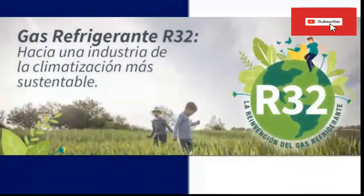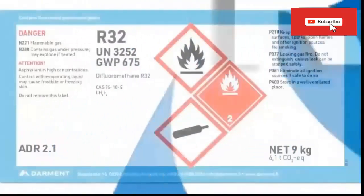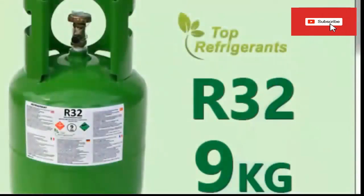The system that works with R32 requires sensors, so that if a concentration of at least 25% of the lower flammability limit of R32 is detected, the mitigation system is activated. For example, valve closure is required, or other measures. 5. Detectors are required to have a constantly running self-test routine to ensure that they are functional and fail-safe.